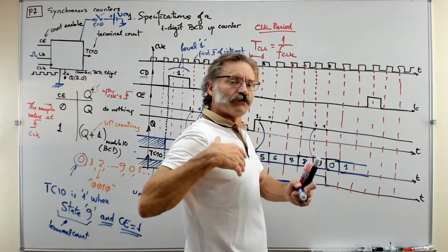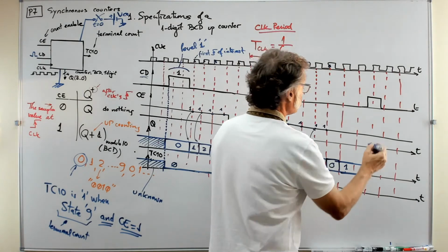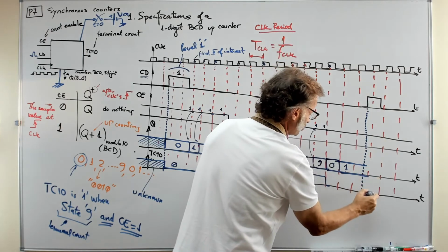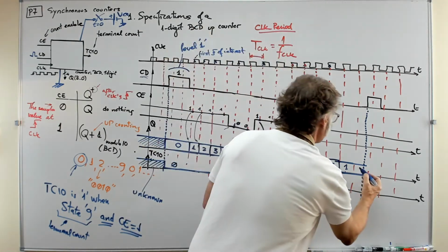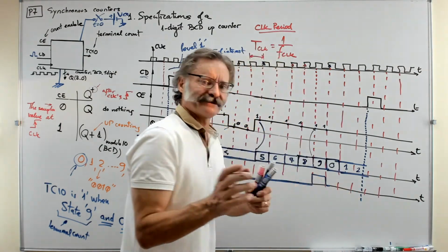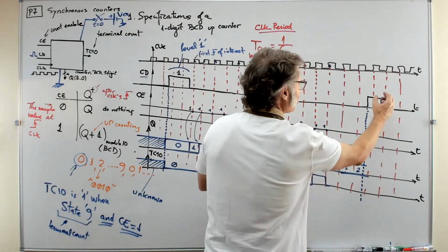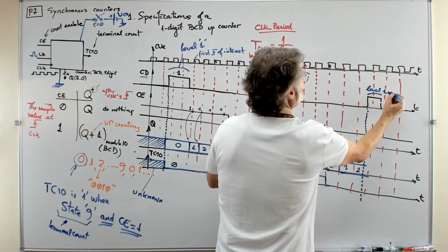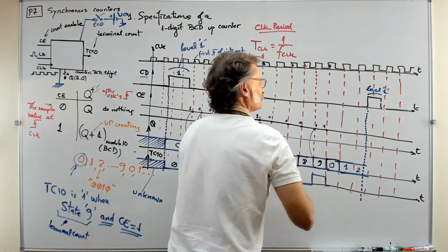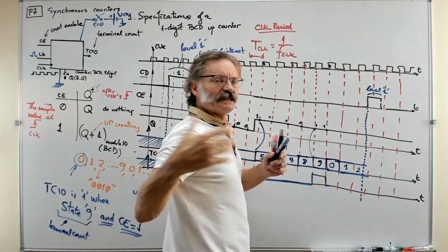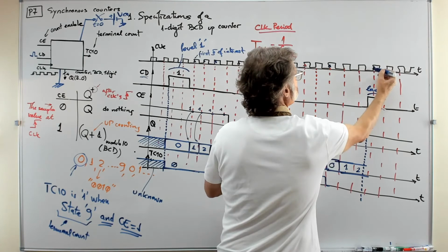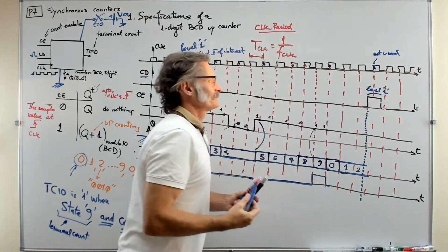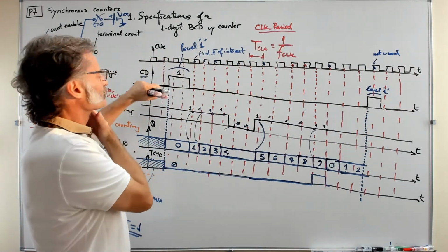But now you are going to force, as you did before, you see, here you are forcing, in between the clocks, the situation. So you see, it was a 2, it had in mind to last until the next rising edge, but you see here you have another time a level 1. So this signal is asserted. So you see, it takes action immediately without waiting for this clock. So this clock is useless. You see, this is not used because it's overshadowed by the presence of the clear direct value.